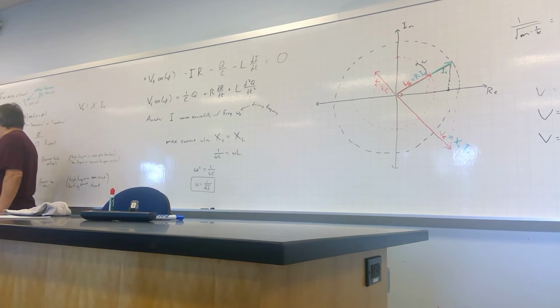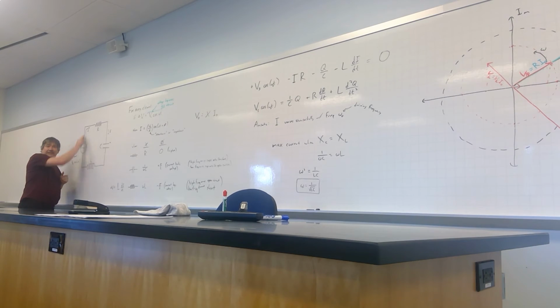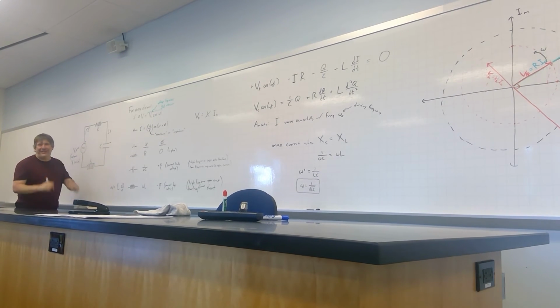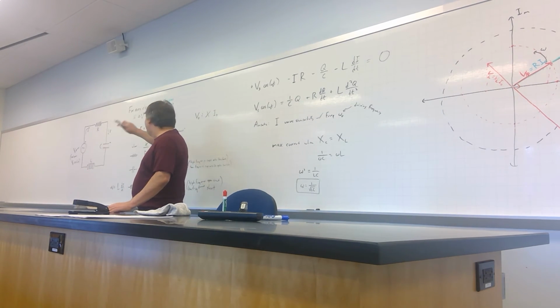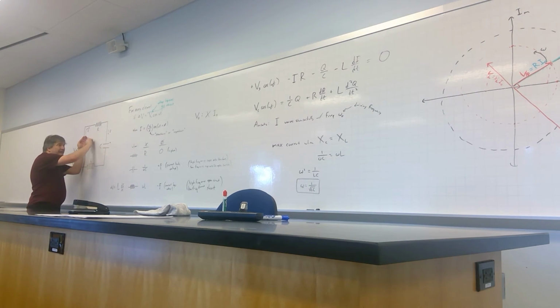If I had just set a DC battery here and charged up the capacitor and then switched the battery out of the circuit, and I know on the exam, switching the battery in and out of the circuit turned out to be a whole little conceptual headache in itself, but if I flip a switch so the battery is no longer in the circuit and the charge can oscillate, the charge would oscillate through this thing at frequency 1 over root LC, and because there's a resistor, the current would gradually die down to 0. So that's like the cat first doing the test of saying, what if I just push on this thing and let it go, and watching that natural frequency.